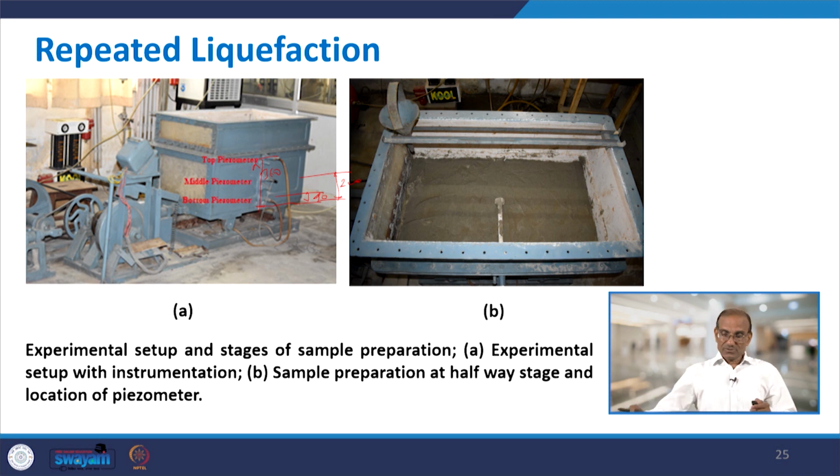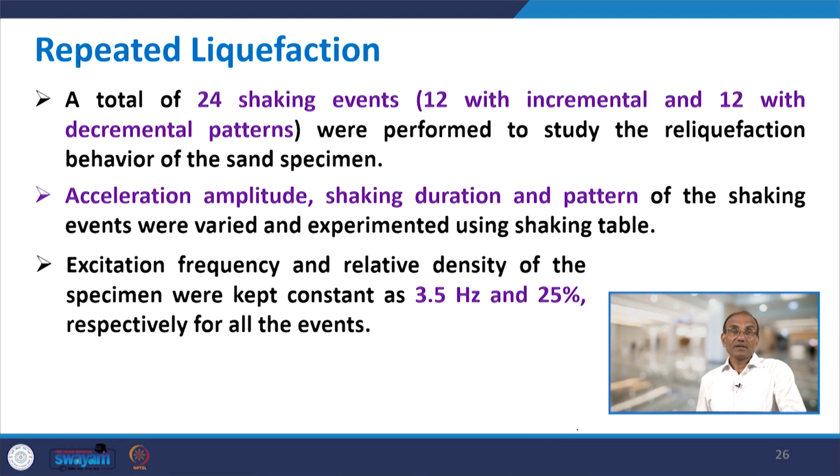In this figure, the experimental setup with instrumentation is shown in part A, and in part B of this figure, sample preparation at halfway stage and location of piezometers has been shown. For this study, a total number of 24 shaking events were performed, and out of 24, 12 shakings were given with incremental and 12 with decremental patterns to study the reliquefaction behavior of the sand specimen.